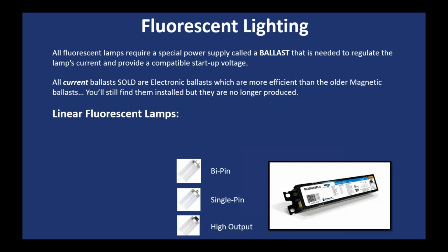But a lot of people haven't understood that. There are even a lot of architects who didn't understand that and went ahead and spec'd them indoors. Folks, it makes no sense to have high output lighting inside. For those who have that in place, we need to get that changed out for their own good, because they're not getting any more light out of those. They're simply using a lot of electricity to produce the same light that they would be with something that's using much, much less energy. Makes a huge difference to them.